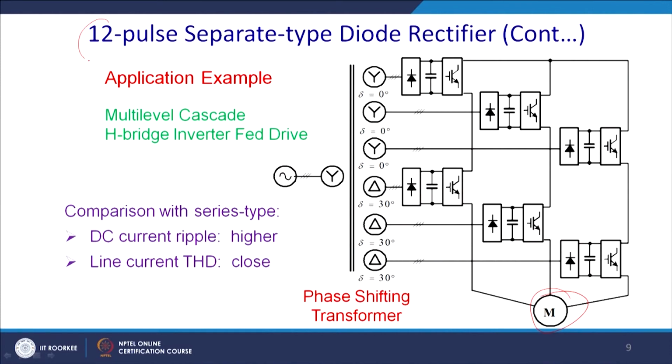Now, in the same way we can have this, something that Siemens brings into the picture. You can Google or search the brochure of these Siemens drives, it is called Ruby drive, they have also changed to new nomenclatures. So, that was for the 24 pulse, but I have derived it for the 12 pulse separate diode bridge rectifier type to simplify the structure of the system.